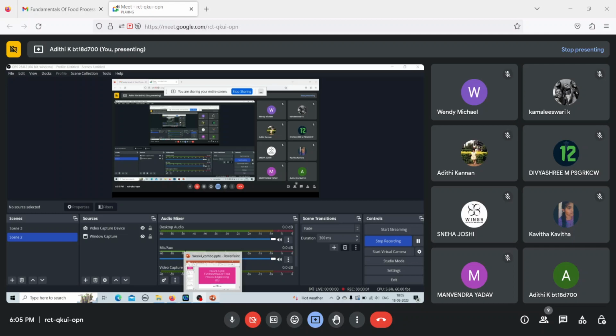There is no such thing as XV here because only water vapor is being evaporated. Solids do not evaporate. So whatever solids you have will come through the product stream only. This will only have water vapor. So even if you have something known as V into XV, your XV will always be equal to 0. Is this part clear? Are there any doubts in these mass balance equations? Because we will be continuously using them throughout each and every problem.